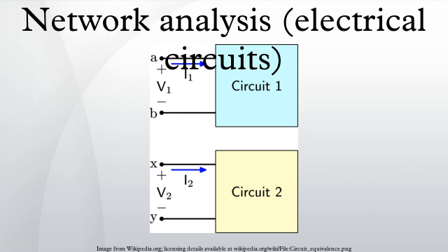Two-port parameters. The concept of a two-port network can be useful in network analysis as a black box approach to analysis. The behavior of the two-port network in a larger network can be entirely characterized without necessarily stating anything about the internal structure. However, to do this it is necessary to have more information than just the A(jω) described above. It can be shown that four such parameters are required to fully characterize the two-port network.